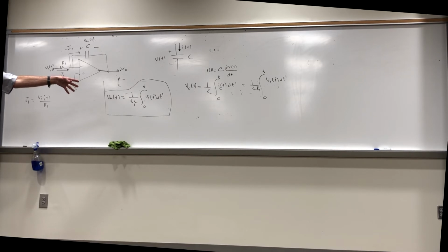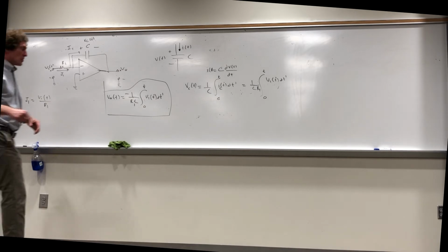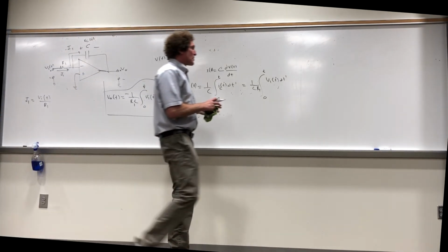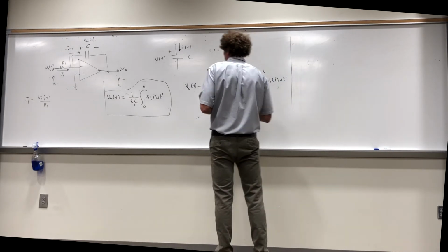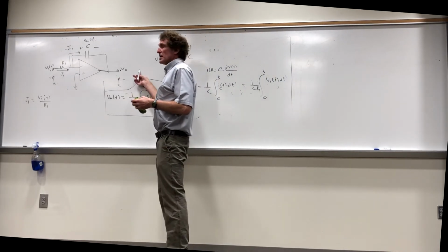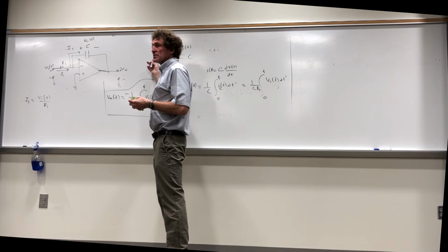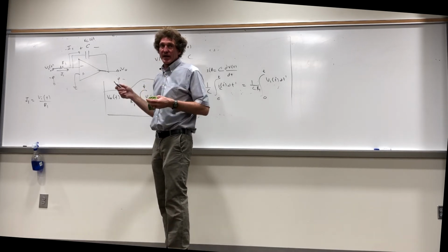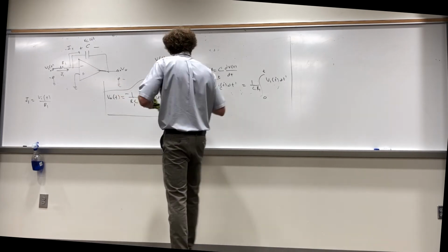Are you with me? I'm just going to do the differentiator next, and then it will go into the S domain, because that's really the important part. So that's an integration circuit, but in order to get it to work right, you would actually put another op amp with resistors of equal value in front of it, so you would get the negative effect canceled. Are you with me? But that's it.